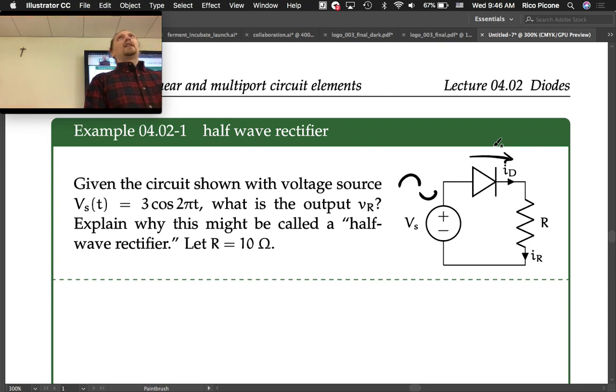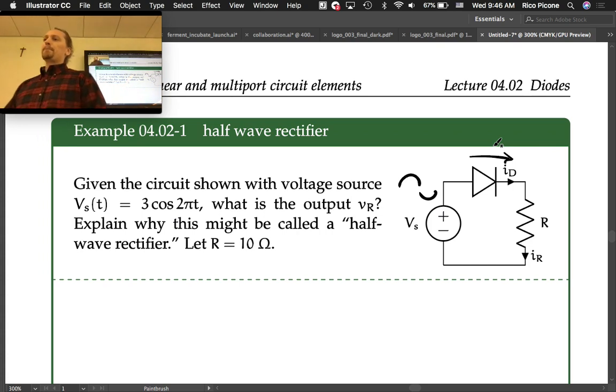I will say that these types of problems, nonlinear circuits with diodes in them, start to lend themselves to simulation. Okay, so simulation can be done using the nonlinear equations, and using the same methods that we start with, we can write all the equations down, but then instead of solving the differential equation ourselves manually, we will plug that into MATLAB, say, and we will run a simulation.